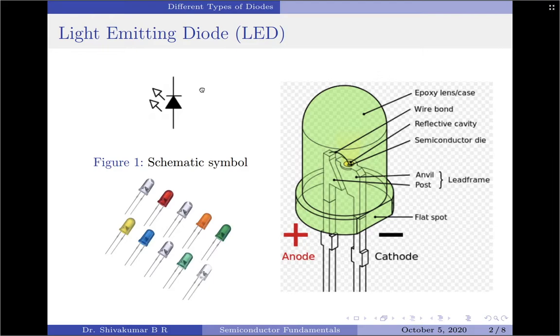In order to achieve this, LEDs are not formed just by using silicon as in a typical switching diode. Instead, somewhat more exotic materials are used. From an analysis or design standpoint, the important thing to remember is that the forward voltage drop tends to be noticeably higher than that of silicon, which is 0.7 volt.